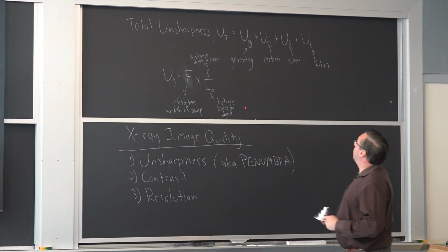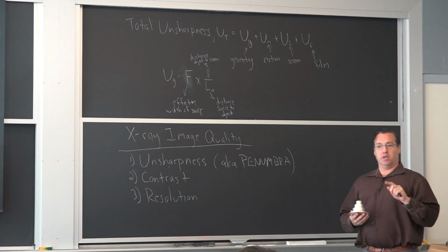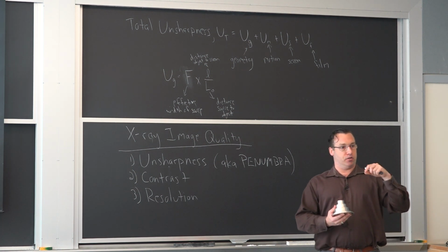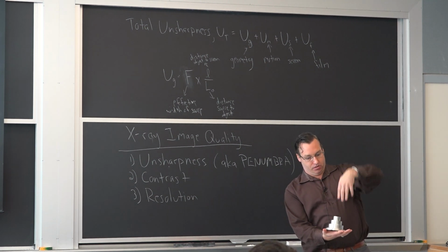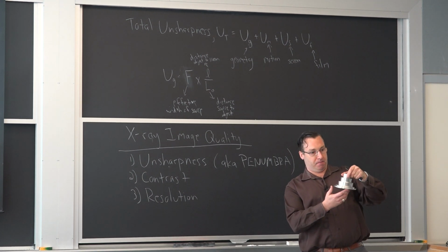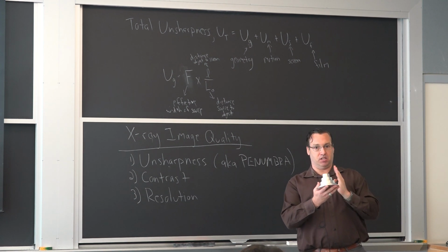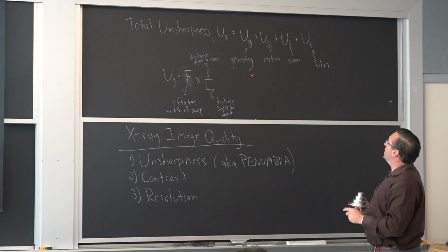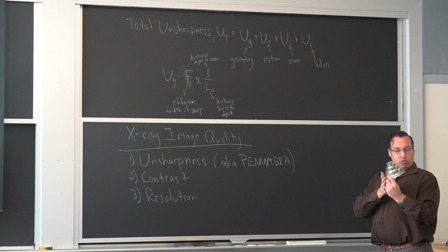You also have, for computed tomography, a source of noise because, as opposed to film and digital radiography where the sample remains flat and you just send the X-rays onto the sample, in computed tomography the sample actually rotates 360 degrees and it takes multiple slices of a single sample. So you have an added source of noise from the motion of the sample on the turntable.